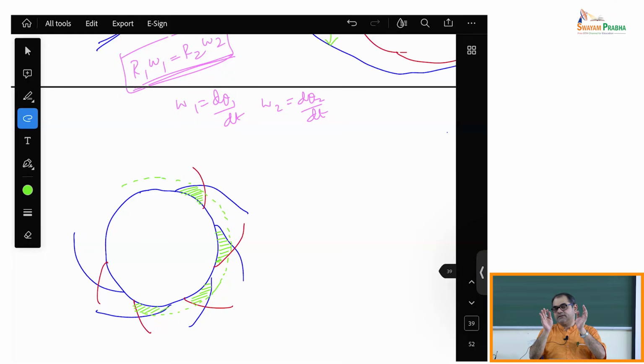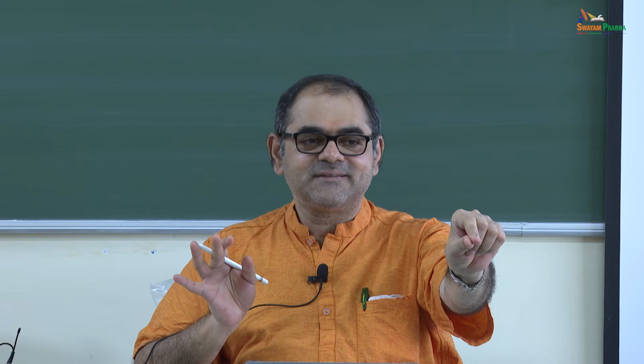And the beautiful thing is both sides of the teeth are involutes of the circle. So the gear can work in both directions. The radius of the circle is at your control, and where you want to place the center of the gear is also at your control. You can simply make any two such gears and match them.